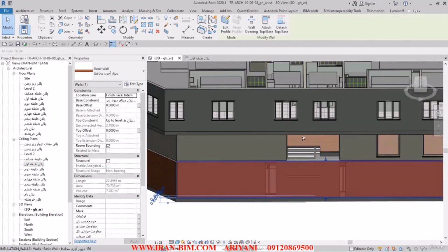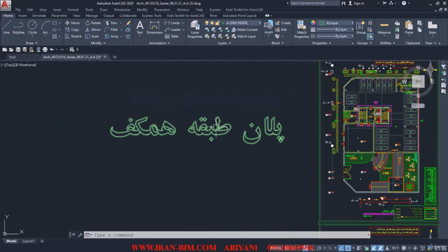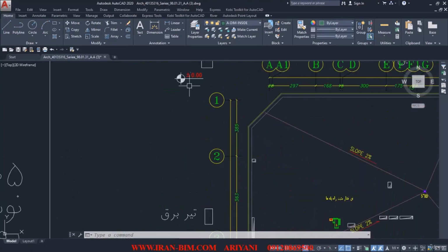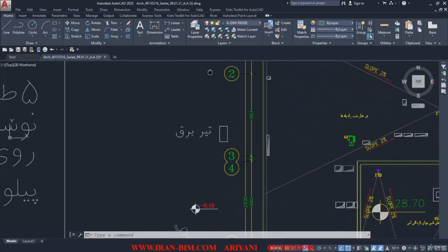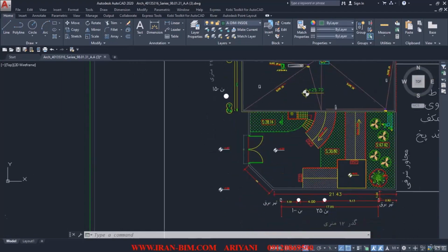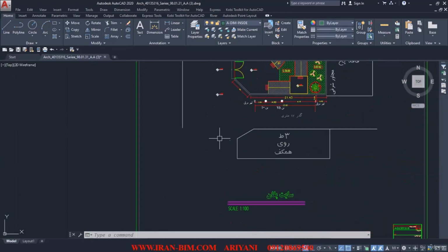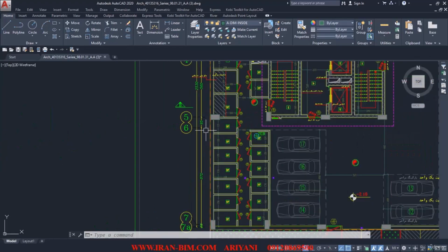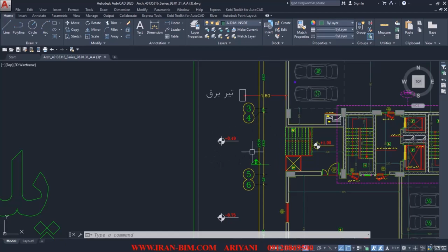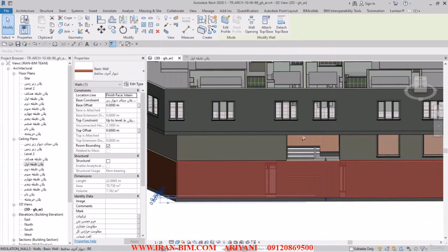According to the CAD file that we have, the floor in this part has a slope. Let's take a look at it here. Let me just pull it up. As you can see, we have 0 here, then minus 0.49 here, and then here we have minus 1.23, and then minus 1.5. And then the slope continues, as you can see here. So in this part, we have minus 0.49. Just have that in mind. Let's go back to the Revit file, and we'll go to the plan right here.